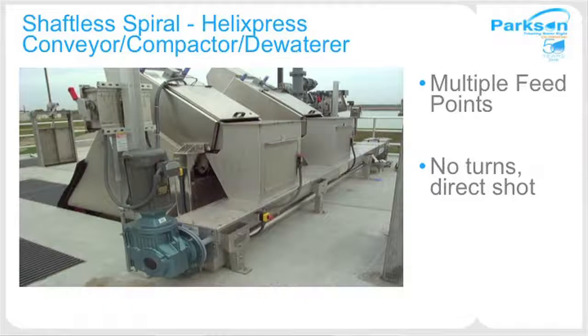And here we see an installation with 2 Aqua Guards and a Helix Press. As you can see, on the shafted spiral designs you cannot typically have multiple feed points, but with Helix Press you can have multiple feed points and feed multiple screens into one conveyor or dewaterer. But you cannot have any pipe connection, so you cannot do any turns or drag the screenings in another direction. So you would need another conveyor if you have to move it somewhere else.